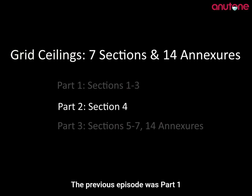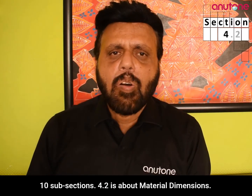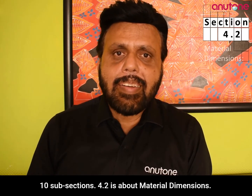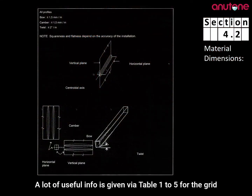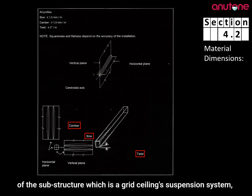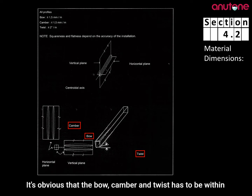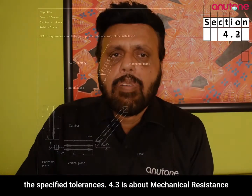The previous episode was part 1 and now this episode is part 2, which is section 4 with 10 subsections. 4.2 is about material dimensions. A lot of useful info is given via tables 1 to 5 for the grid components. Important to note is the bow, camber and twist of the substructure, which is the grid ceiling suspension system, skeleton in the case of Anutone. It's obvious that the bow, camber and twist have to be within the specified tolerances.